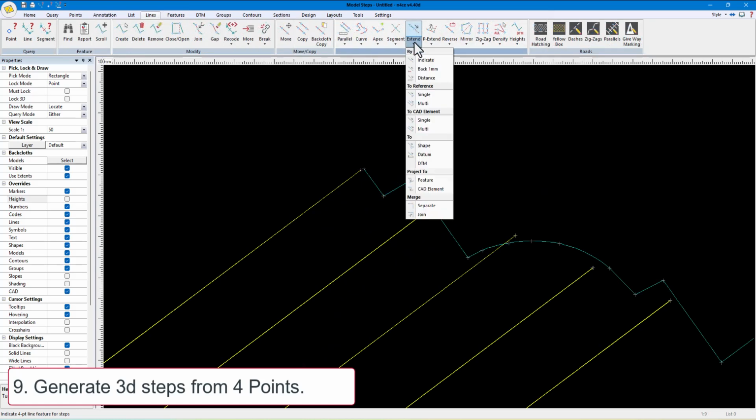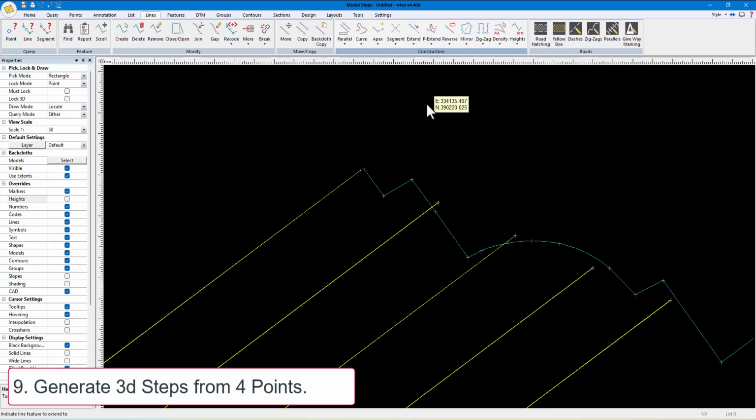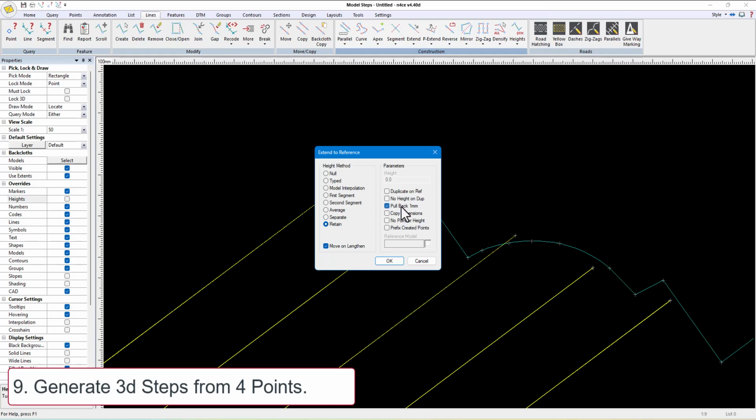If needed, the line work can then be trimmed to fit any containing features, and pulled back 1 millimeter to allow them to be modeled in a DTM.